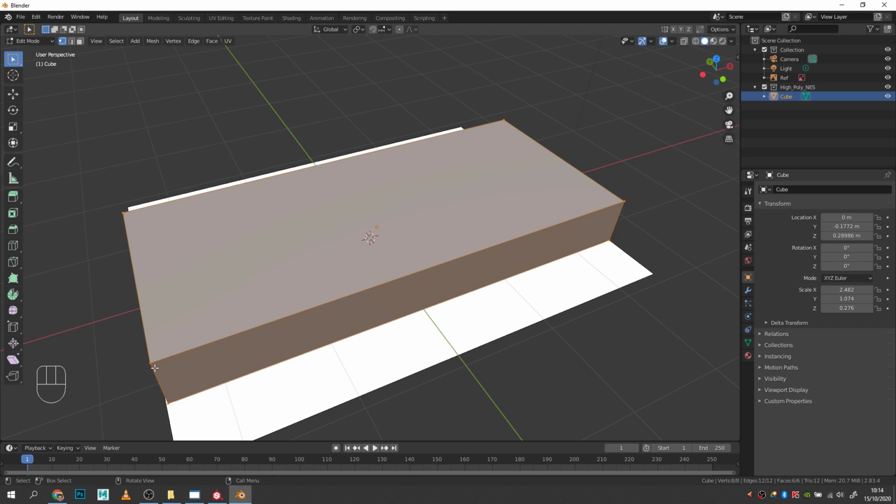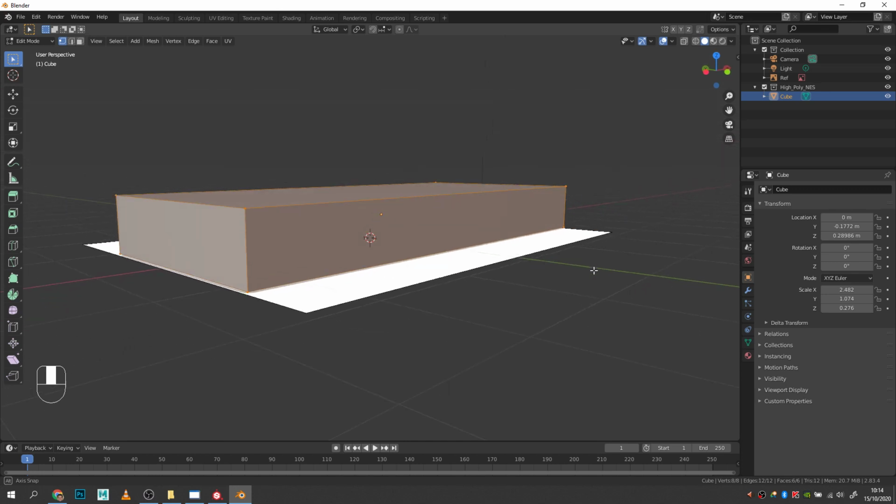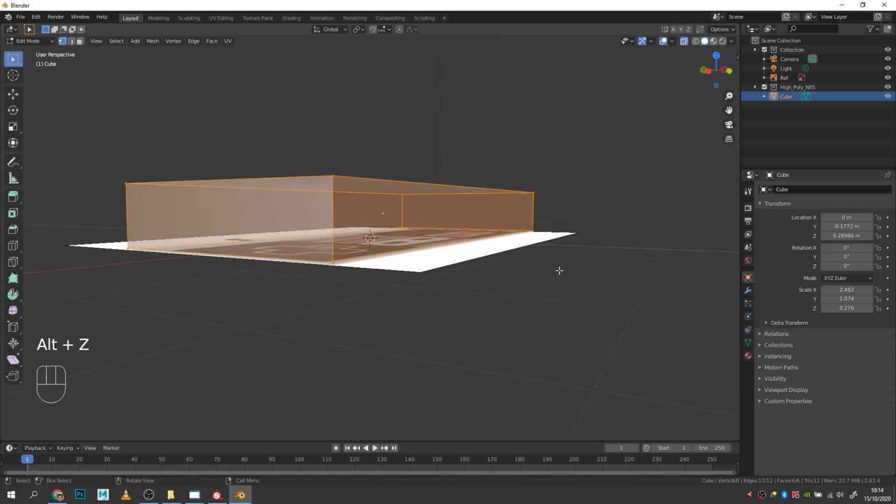Okay, first thing we want to do is select each of these corners, and we want to chamfer them or bevel them. So in order to select all of them at the same time, I'm going to go into see-through mode so we can see the one in the back, and then I'm just going to click and drag this little marquee, and that's going to select my edges if I have edges turned on, which I don't currently. So 2 on the keyboard is edges. You can see it's changing them up here.